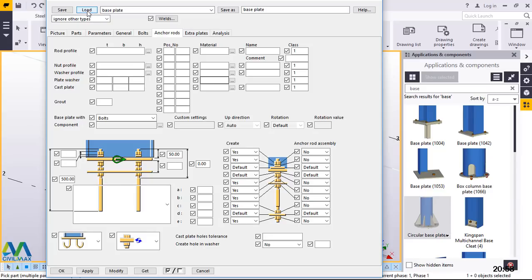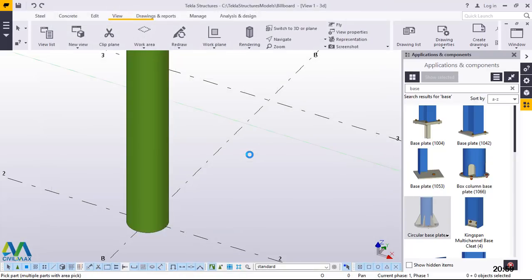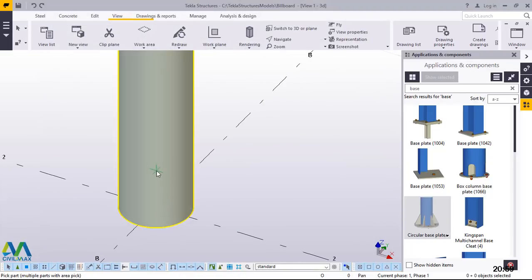the base plate settings, and remember you can use this and save and give it a name of your choice. Once you've done that, just click save as, and the settings will be saved in your system. So whenever you want to apply the same connection, you just go ahead and pick and put it into action. Now I'll go ahead and click load, come here, modify, I'll accept that, I'll give it an OK here by clicking OK button. Then I'll come at the bottom end here and click on this member, then snap right at the bottom end right there.